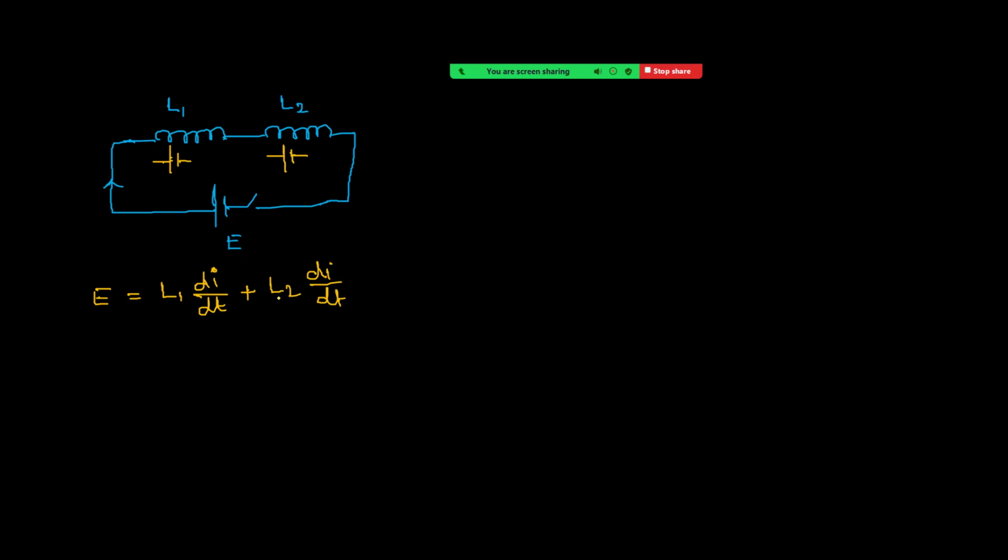Now the question is, for this combination, what is the equivalent inductance? See, what is the meaning of that? If we want to replace these two inductors with a single inductor, I'm drawing here. If you want to replace both the inductors with a single inductor, and if we connect the same battery, then the EMF must be again the same. So for the same change in current, we have to get the same EMF.